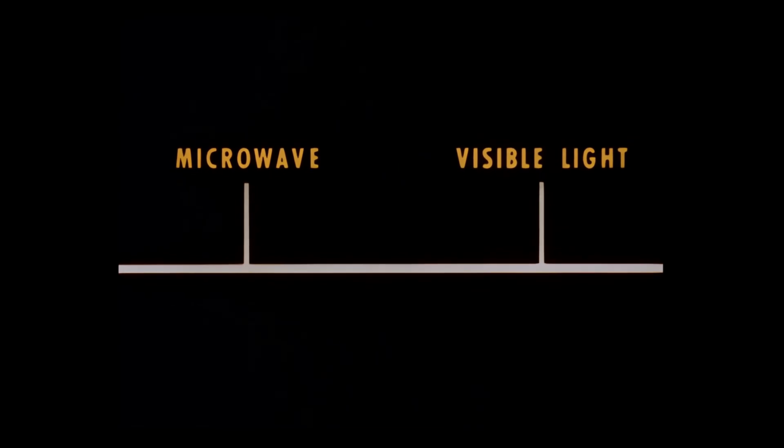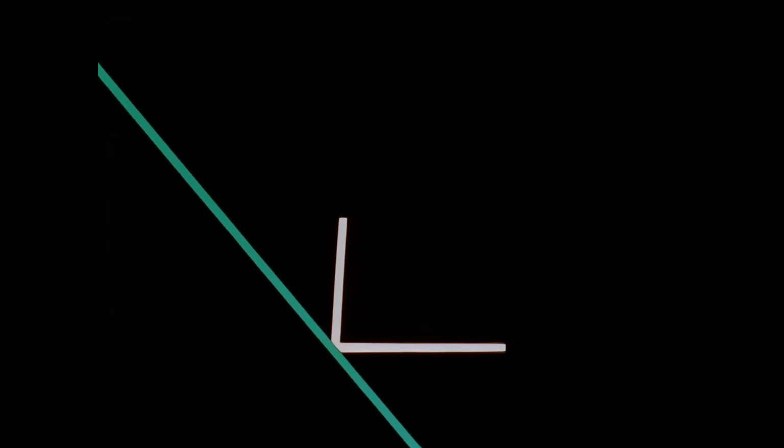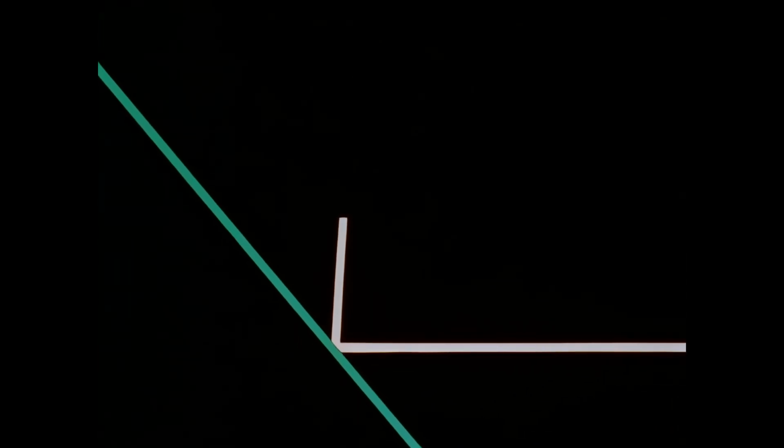Let's briefly review a simple optical principle. Here's a plane surface. Light, striking it at this angle, will be reflected at an equal angle. If we arrange a number of such reflecting elements so that the reflected rays emerge parallel to each other, our reflector becomes a parabola. All path lengths from the focal point will be equal. Energy will thus radiate in a plane of uniform polarity and intensity.